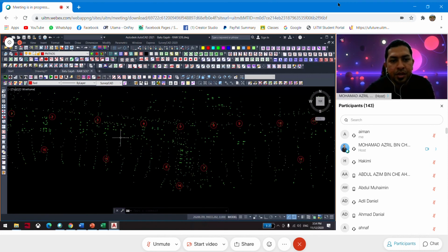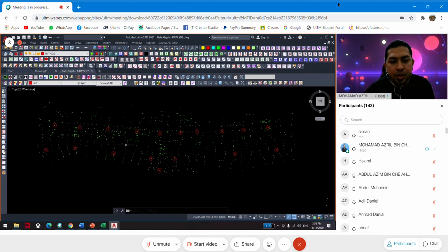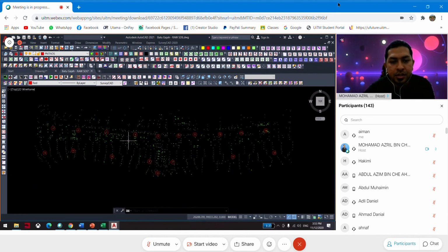So the point is, once you want to process the stadia data, you need to know the known point and the elevation of the station. Make sure you apply the corrections in your field book correctly before you have the final bearing and final distance, which you will use to calculate the coordinates. Those coordinates you will use in the stadia.